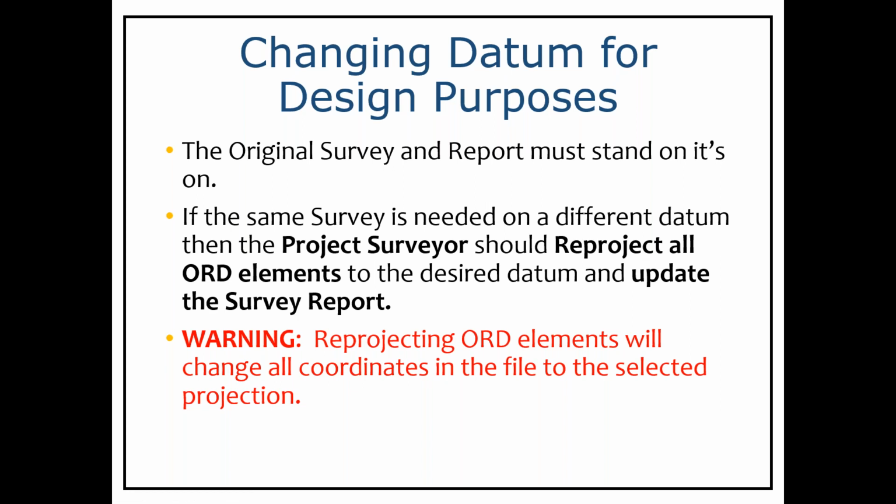These datum changes are not exact, and even NGS, who wrote the NCAT program, will tell you they're not exact, and even theirs is not exact. There's going to be some slop. So I put a warning down here. Reprojecting ORD elements will change all coordinates in the file to the selected projection. So don't do it. Only your surveyor should do this, and we don't recommend the surveyor does it either.